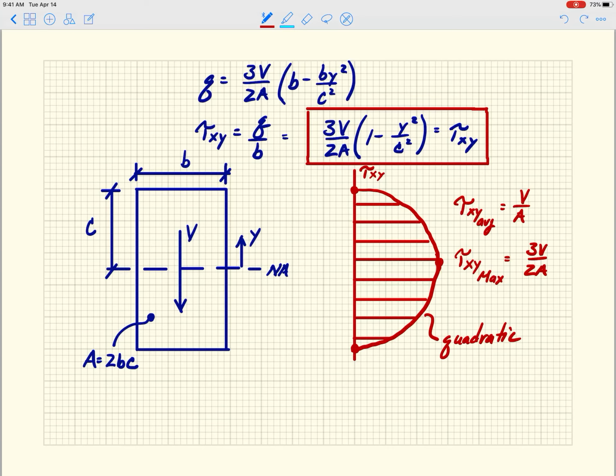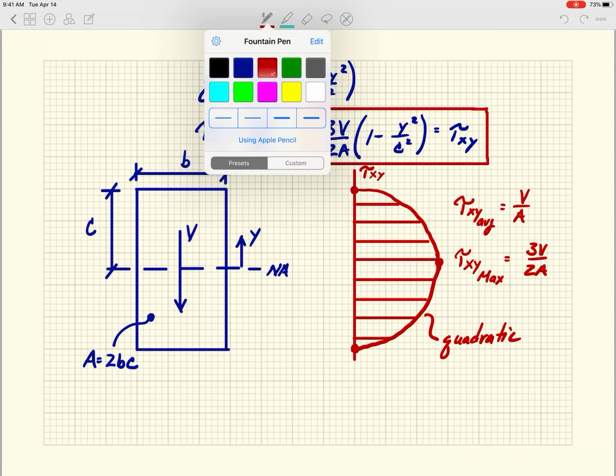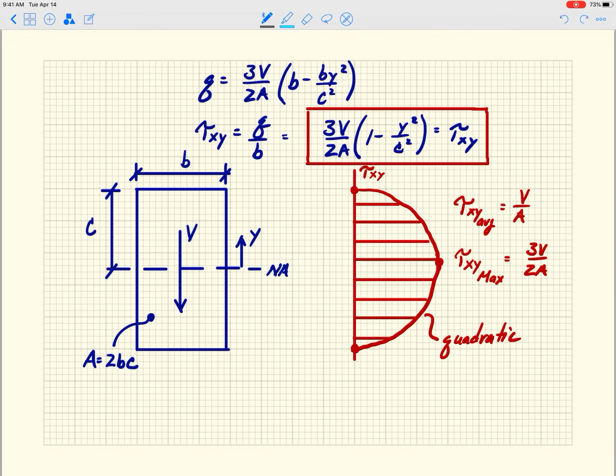But for the time being, with this rectangular section, there's a few things that we can note. One is that where the flexural stress is a maximum, the shear stress is a minimum. So that would be at these ends here. So if I'm going to, let me do this in gray, and if this confuses you, please just ignore it. I know I say that a lot.